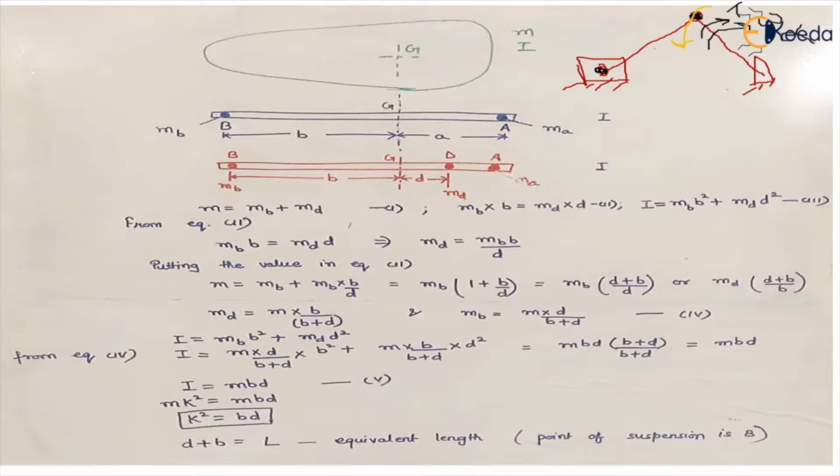Initially, whatever torque or alpha we were giving to the system was sufficient to overcome the inertia effect of the already existing mass at the crank pin. But now, because we have added the mass, it will reduce the angular acceleration, or the turning moment of the system, which is not desirable.